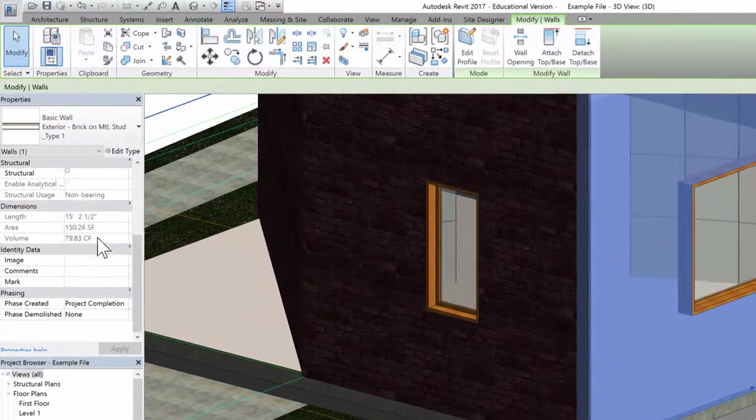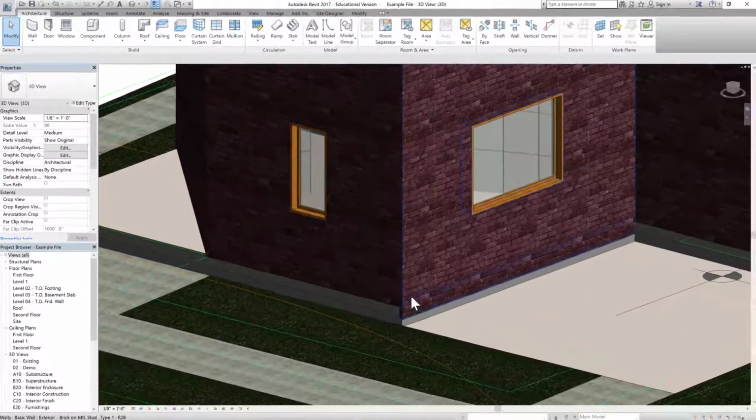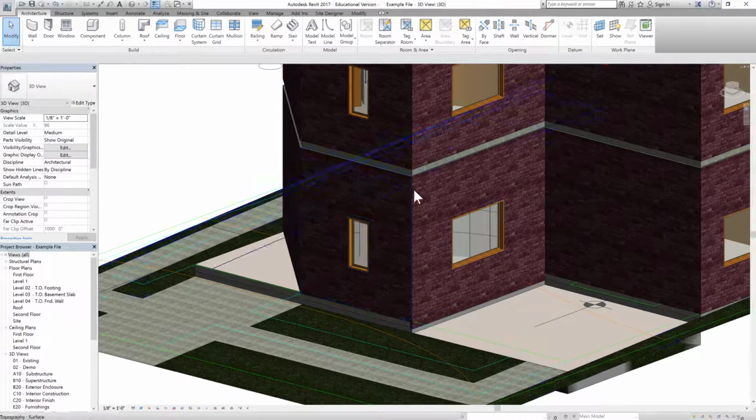And now, once you go into the properties of this wall, you have base extension that is highlighted here. So let's go ahead and give an extension of -6.5 inch because that's the thickness of the floor. And as you can see, it brings down those three layers and it covers the floor. We can do that for all the walls on the first floor.